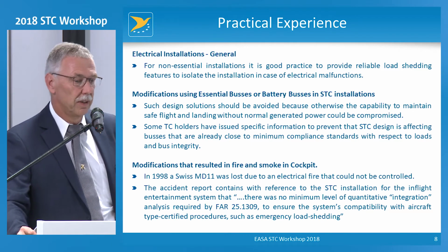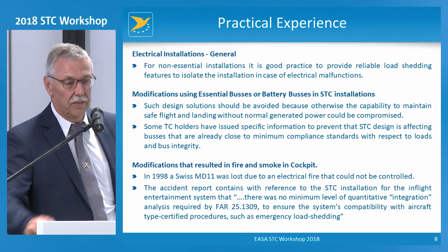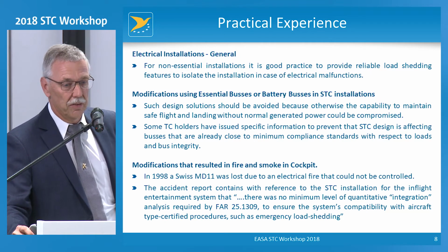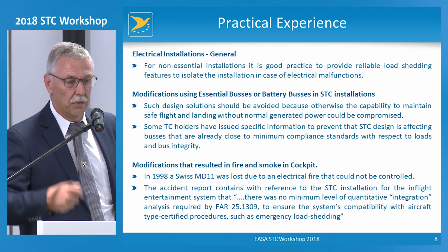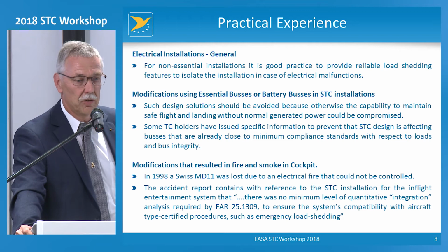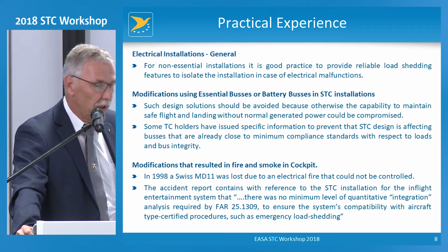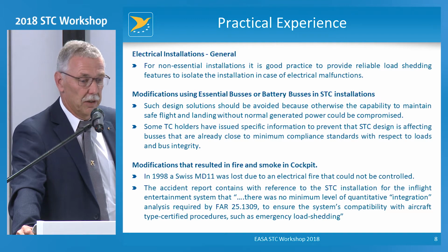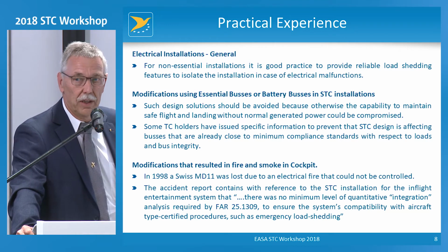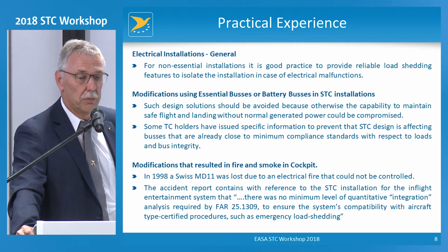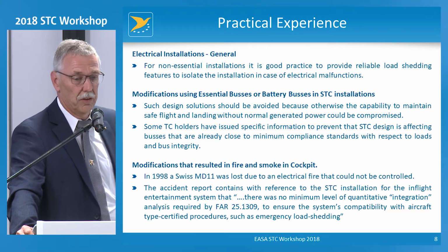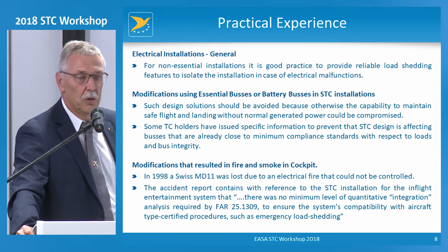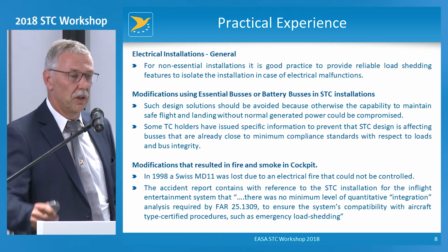Another thing that is important with electrical installations is that some of the essential buses on some airplanes are pretty much loaded and do not cope with a lot of additional loads. So for instance, Airbus has issued guidance and documents to actually prohibit, which they are not allowed to, but they want to prohibit that people tap new equipment and users on their essential buses, which are very much close to the limit.